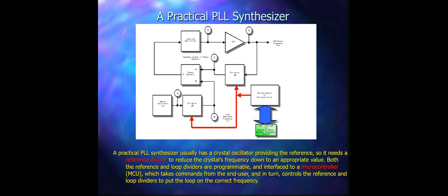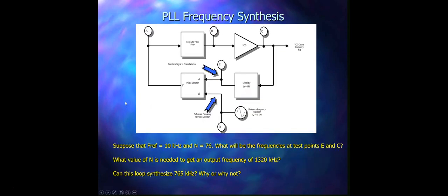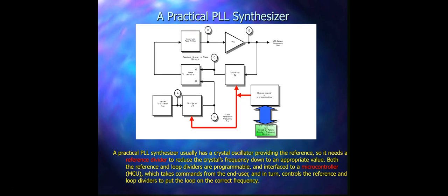Now the next is a practical PLL synthesizer, and you see how it is different from the previous block diagram of the PLL synthesizer. In this one, we have extra components added over here: a master oscillator, a divide by R, and a microprocessor or microcontroller block here.